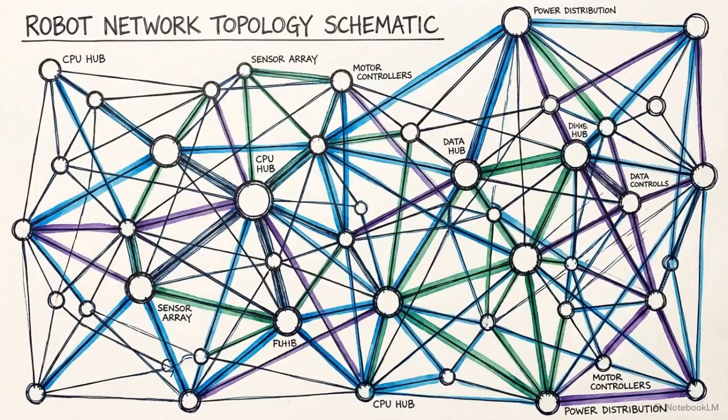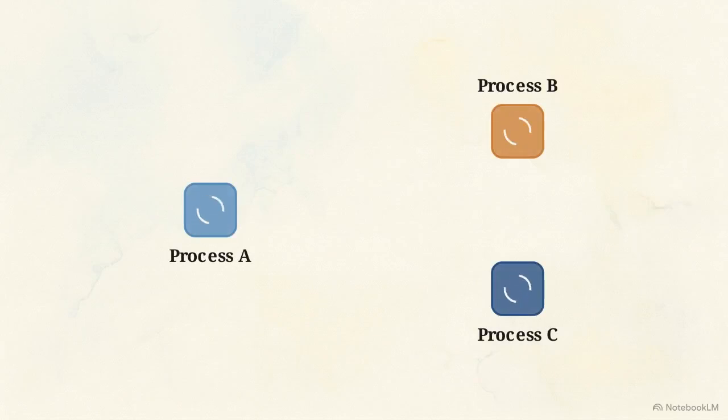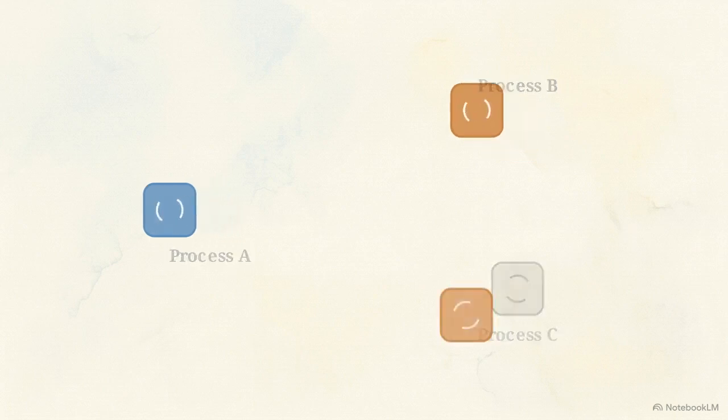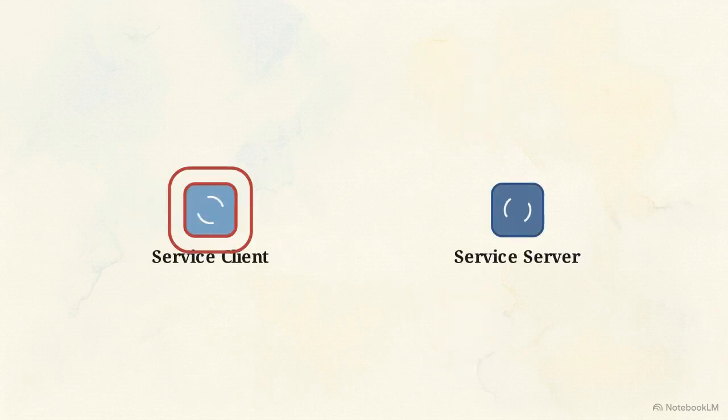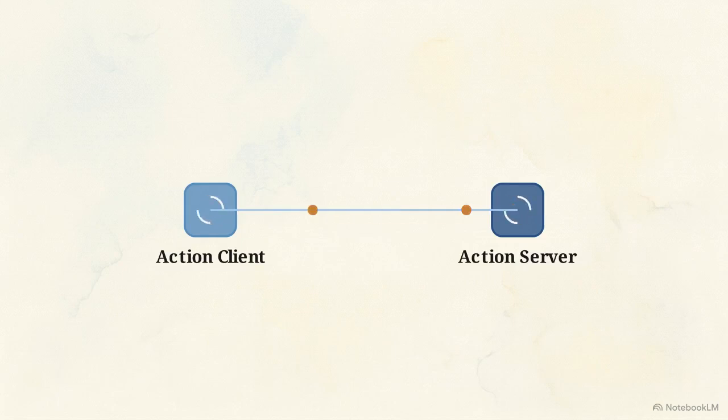This brings us to the complete decoupled architecture. The entire quadruped is driven by multiple independent processes, communicating simultaneously. Nodes isolate the logic to prevent a single failure point from crashing the machine. Topics blast lossy, continuous sensor data across the network to maintain real-time hardware synchronization. Services lock execution states to ensure discrete commands are received and executed. Actions track long-running asynchronous behaviors while allowing for immediate cancellation.